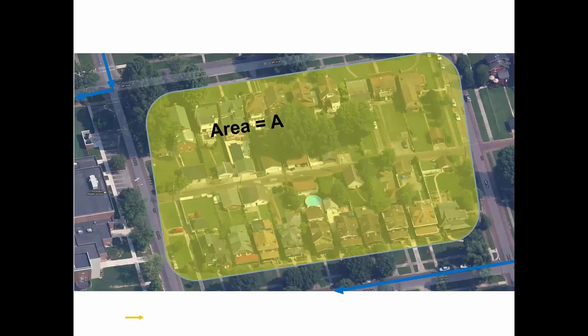Sometimes if you have a topographic map that shows contour lines, you can use that. Or there's Google Earth, the program that's freely available from Google. Your cursor, as it moves over the map, tells you the elevation. But this area, the contributing area, is just, we're saying all of the runoff water in this area is going to be flowing to a common discharge point. So we measure a certain area and have delineated it based on looking at where the curbs and gutters are, and being confident that all of the water that falls in this area is flowing towards the same spot.